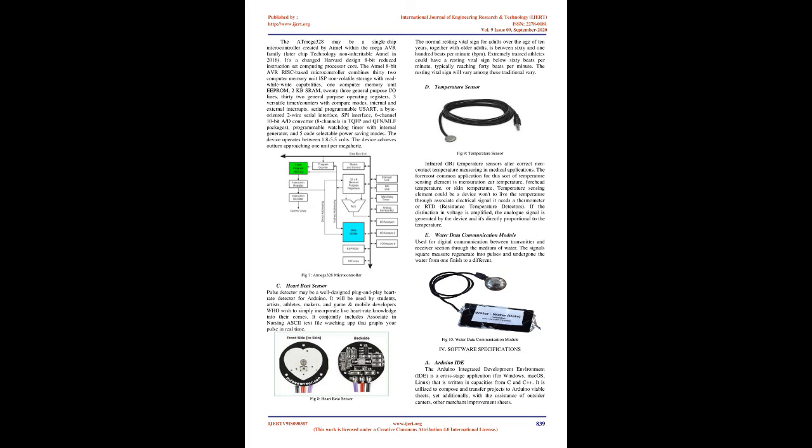TQFP and QFN/MLF packages, programmable watchdog timer with internal oscillator, and 5 software-selectable power-saving modes. The device operates between 1.8 to 5.5 volts. The device achieves throughput approaching 1 MIPS per megahertz. ATmega328 microcontroller.